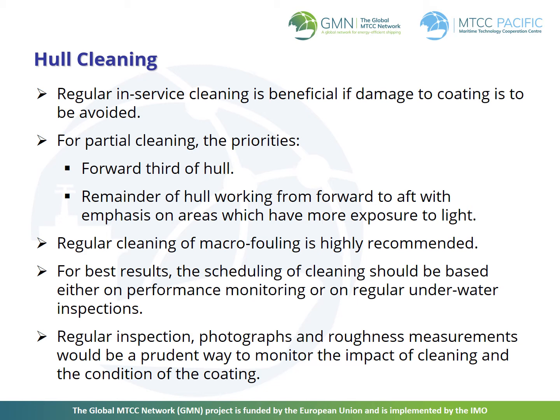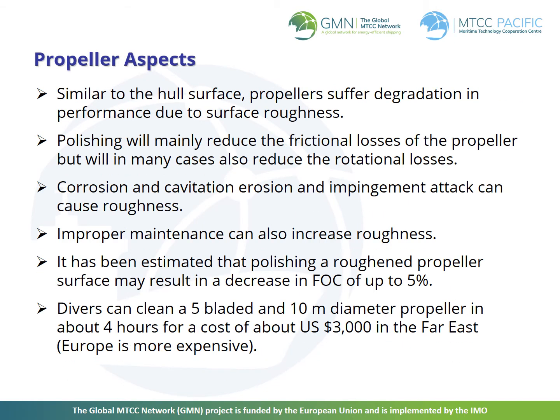For example, the removal of macro-size fouling is difficult to be done without the removal of a significant amount of paint. If anti-fouling is applied in different color layers, then these colors can be used to monitor paint removal during the cleaning process.